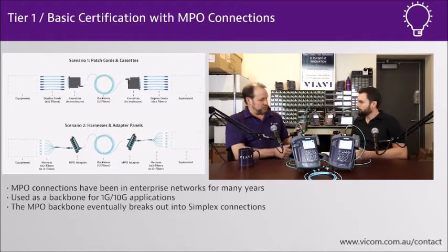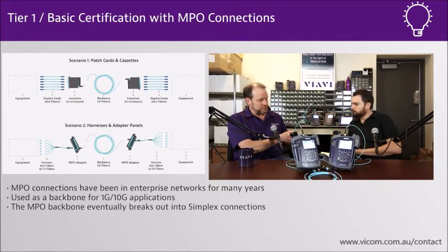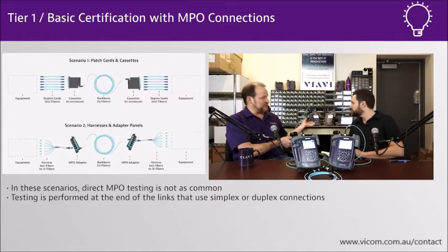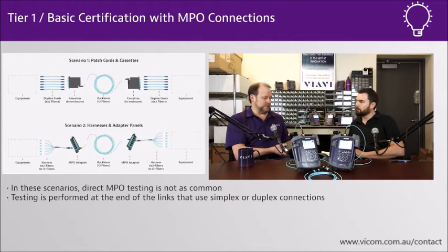Yeah, so this is your cassette. You've got your 24 fibers coming in at the back through MPO, and these need to be inspected, but then your test is done with a classic OLTS by testing each of the individual LC drops. So in this case, you really don't need to test the trunk assembly. If you do need to troubleshoot it, that's where an OTDR would come into play, and then you can look to find out where a specific fault is. But typically with those trunk assemblies, your issue is the connections that you have, the MPO connections.